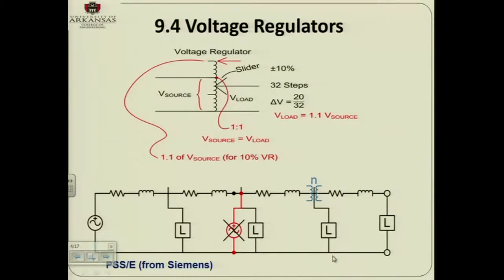So the best way of solving the homework is you run that, then you identify those buses where you have a large reactive power. Why are you not going to put a capacitor on every bus? Expensive, cost. 10 cents per kilowatt hour cost in Arkansas. If you talk to any vendor of demand side management solutions, they are going to tell you, we don't try to sell them in Arkansas.